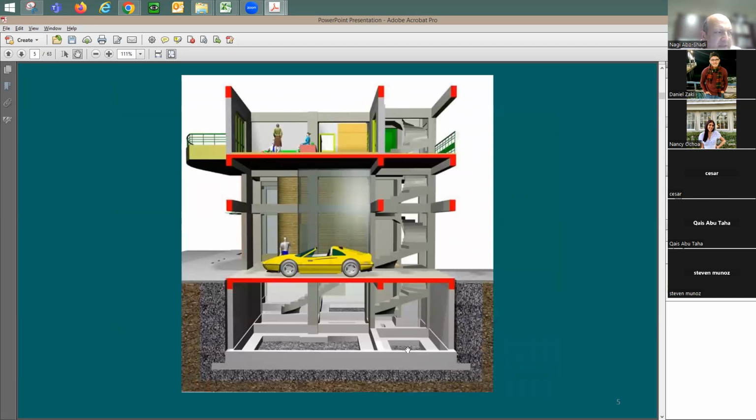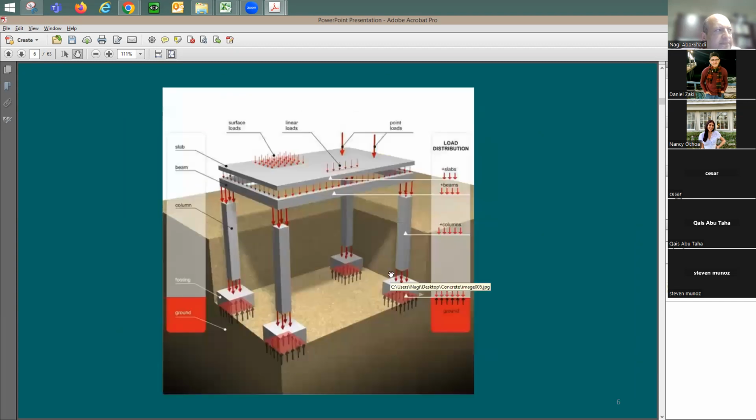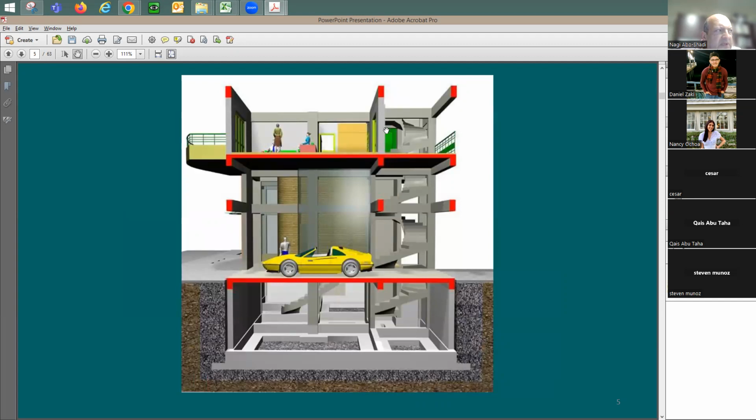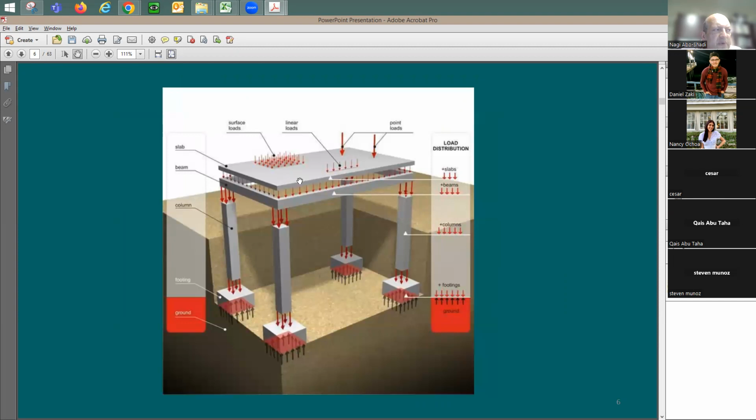Here's one pavement, and then you see here some column footings. You can call it a pad or a column footing. And under the walls here, you're going to have continuous footing for the wall, right? Their job is to take the loads from the top levels and transfer it to the soil. This is going to be the load path that we looked at in this slide before. You can have point loads, uniform load, like service load, or line load, transferred from the slab to the beams, to columns, to footings, eventually to the soil.